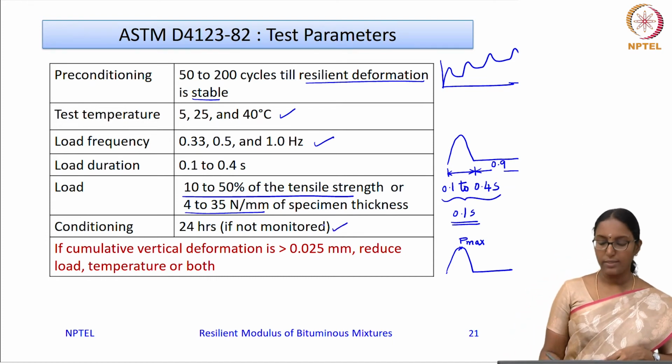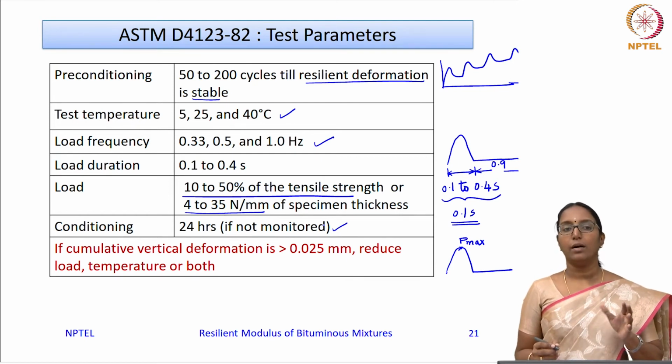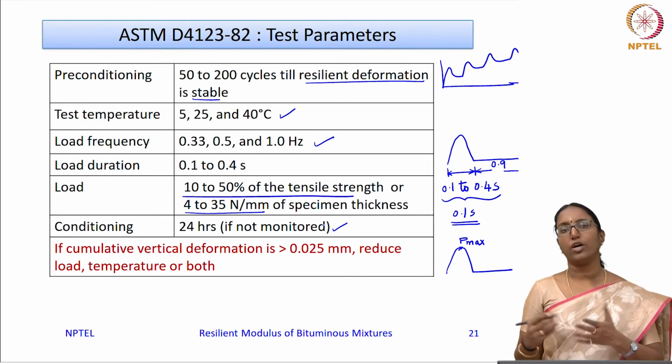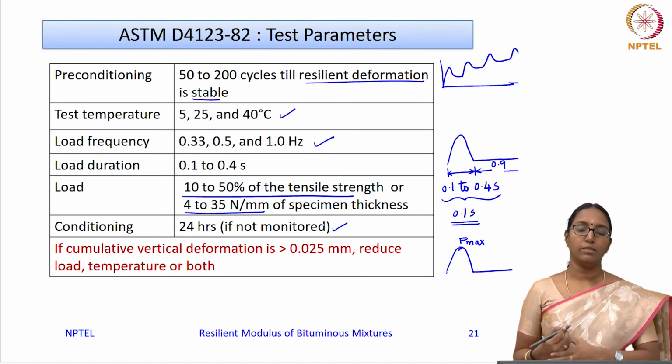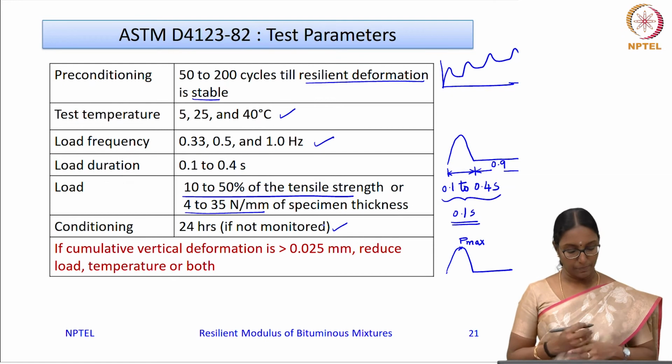Now the conditioning is that at every temperature you are testing, you should condition the sample for sufficient long time, and if you are not, you can monitor the temperature of the specimen, and if you are not monitoring, you should at least condition for 24 hours.